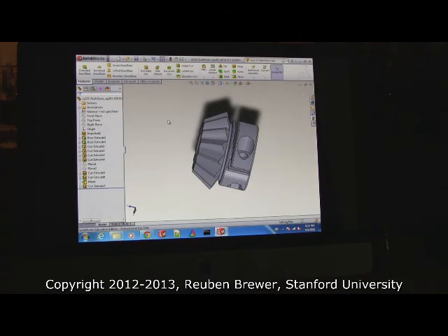Now the last step is I'm just going to explain to you what we just did and why we did it. Quick question. So we did fillet, and in class you mentioned that you chamfer it. So what's the difference? When you 3D print things, sometimes it can get grumpy with sharp edges. If you have the option to chamfer or fillet, I usually fillet just for 3D printed parts. The reason you don't do that for machined parts is it's very annoying for machinists to have to round things, but they have special tools for chamfering, so it's trivial. They can put a chamfer in the time it takes to...